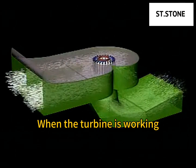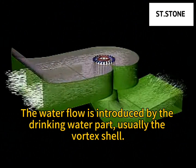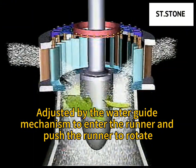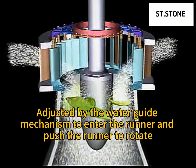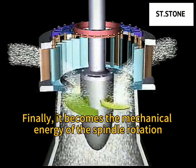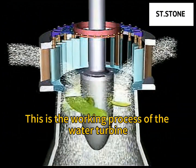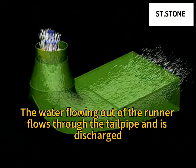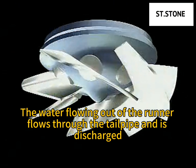When the turbine is working, the water flow is introduced by the water inlet part, usually the scroll shell, adjusted by the water guide mechanism to enter the runner and push the runner to rotate. Finally, it becomes the mechanical energy of the spindle rotation. This is the working process of the water turbine. The water flowing out of the runner flows through the draft tube and is discharged.